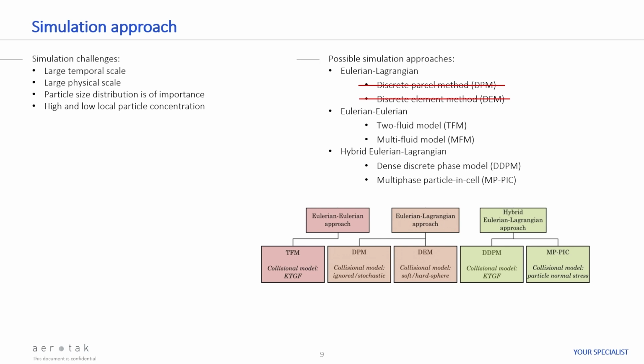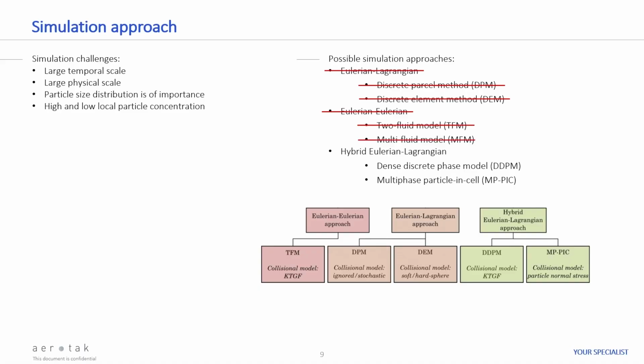Then you have the two fluid models, the Eulerian approaches. Again, we need a particle size distribution. We could do that with a multi-fluid model, but then I would be afraid that the computational cost just basically explodes. So those are out as well.